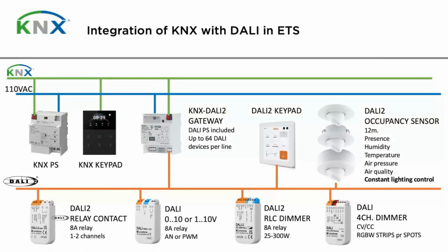So when does it make sense to have DALI instead of just KNX for lighting control? I would say as long as you have more than maybe 25 loads, maybe less. Many people say just 5, I go for DALI, or just 10. If you have a lot of lighting fixtures, like universities, commercial departments, hotels, convention centers, airports, it's very convenient to go for DALI.